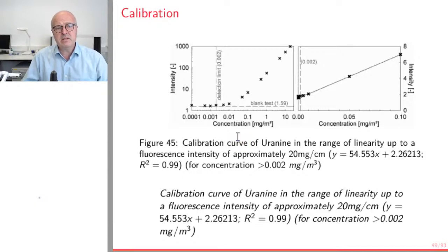Now, you bring the zero sample to the lab, and then you add tracer to create a series, let's say 7 or 10 samples of different concentration over the linear range, and you measure them, and you get the intensity for a known concentration, and this becomes your concentration curve. You will observe that at very low concentrations, below the detection limit, the curve is not linear anymore, so you cannot extend the curve below that.